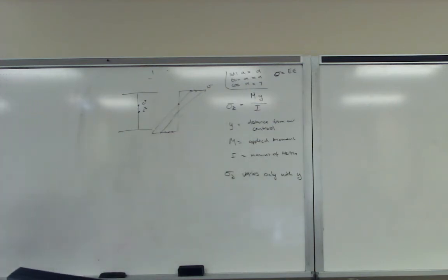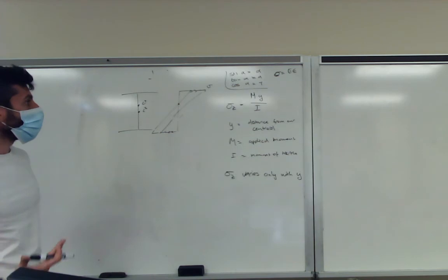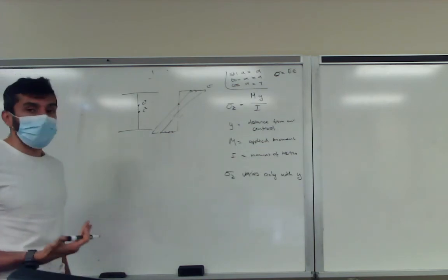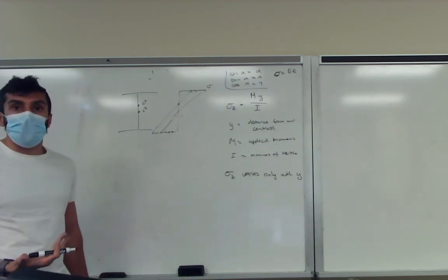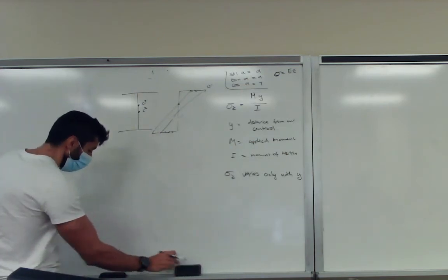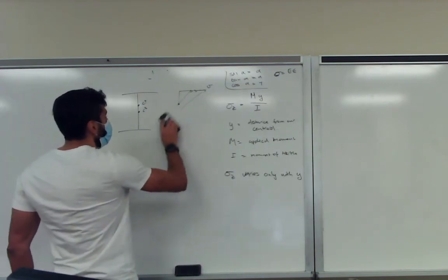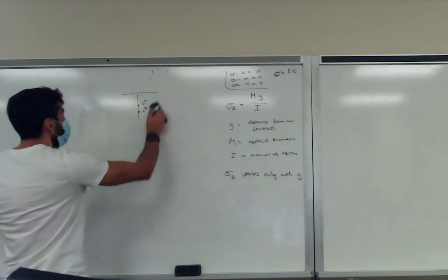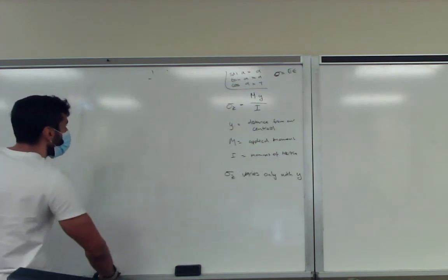So of course, if you're an engineer, you want to evaluate the structure. Say if you have a material given, steel or aluminum, you know those materials have certain failure stresses. So if you want to evaluate your structure, you don't want to evaluate at every point, but you want to evaluate it where the maximum is.